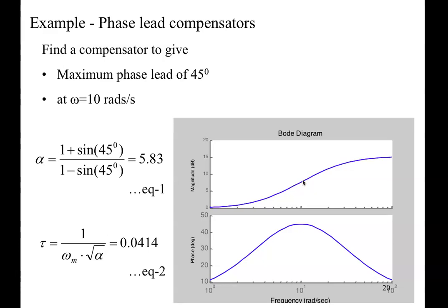Okay, and you add the phase angle of this Ks to the phase angle of Gs. That will change omega 2. It will change the phase margin and so on. But for a particular design, we normally ask, say, we want the overall phase margin, the overall gain margin, the overall crossover frequency. So we need to consider both G and K at the same time.